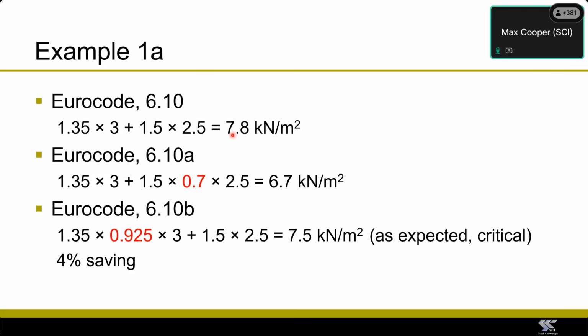That might be enough to just tip you into a slightly lighter beam choice. So it potentially could save you more than 4% steel weight. And I would suggest obviously in many instances these calculations are done by computer models anyway, so it's really minimal extra effort for a potentially useful saving.